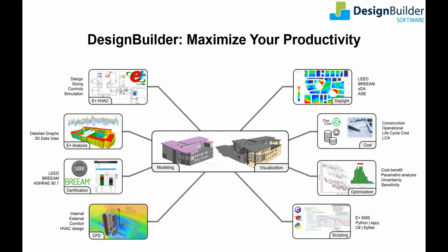Use EnergyPlus to run load calculations and energy and comfort simulations, generating outputs for design and compliance with LEED, etc. Our powerful industry-leading tools include scripting, optimization, uncertainty and sensitivity analysis, and cost. From that core model, you can also run daylighting simulations using the Radiance engine and internal and external CFD analyses. I'll point to some resources on our website at the end where you can find out more.